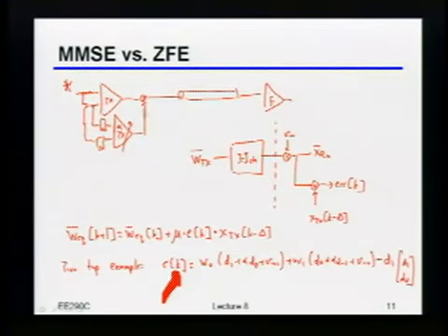So that's kind of a good news, bad news story. If you're using this with a transmitter, you're stuck with zero forcing. If you're using this with a DFE, well, great. I have zero forcing. That's exactly what I wanted. Okay? So you should notice that the update equations you use for, for example, a receive linear equalizer versus a receive DFE are different. Because in one of them, you actually completely want to kill the ISI. And in the other, you want to balance how much noise you have against how much you're correcting for the ISI. Okay? Does this make sense to people?